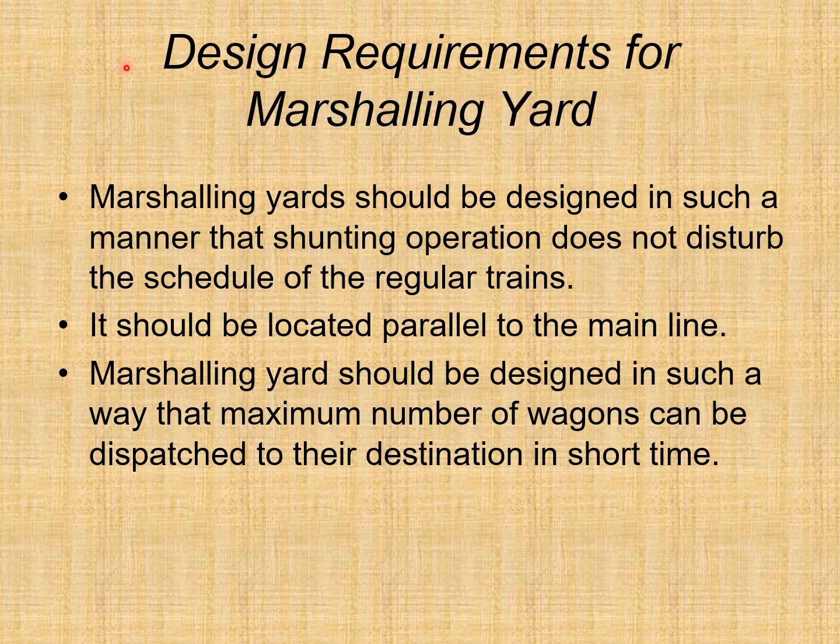So, design requirements for marshalling yard. Marshalling yard should be designed in such a manner that shunting operation does not disturb the schedule of the regular trains. It should be located parallel to the main line.